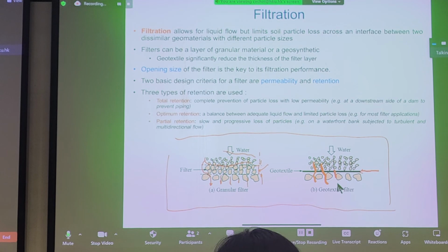For example, the point of a PVD drain is to enhance the dissipation of pore pressures. If you have permeabilities that are too low, you're going to prevent rapid dissipation of pore pressure. So a very effective filtration or filter will cater for two parameters, particularly permeability and also the ability to retain finer particles from entering whatever layer you'd like to use.